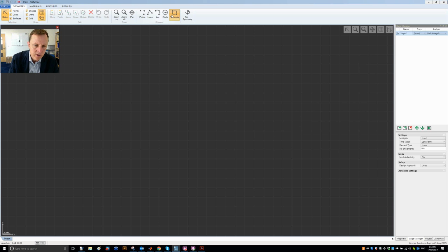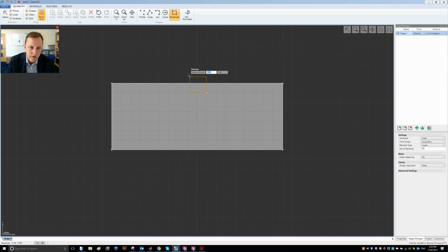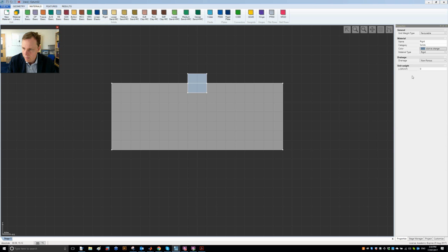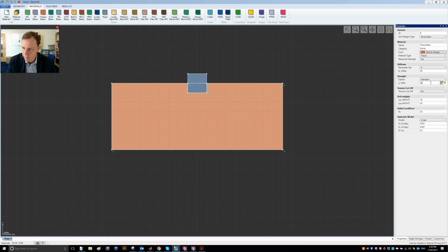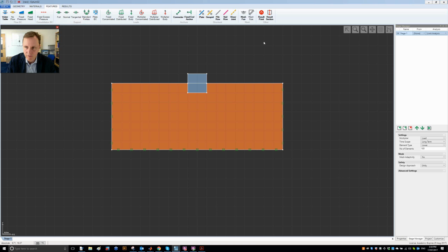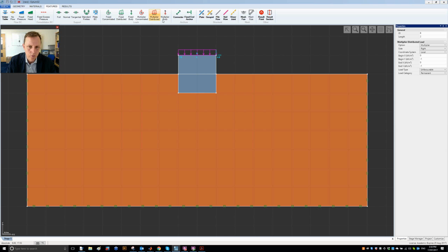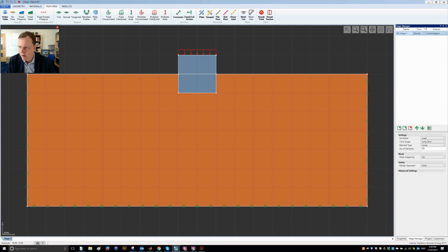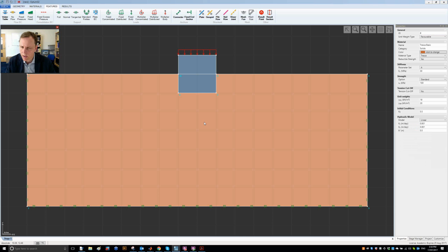So again, I'd encourage you to have a look at the manual. Just very briefly, to show you how to set up a problem and run a stochastic analysis, I'm going to run an embedded footing problem like that. Let's make that rigid. Let's give it a unit weight of, say, 23, and then have a Tresca material. Let's make it 100 kPa undrained shear strength, then standard fixed supports and a load on top here. I'm going to run limit analysis in this case, and let me just keep it at 100 elements, just to get things running quickly.